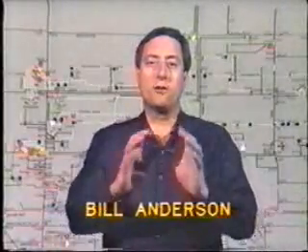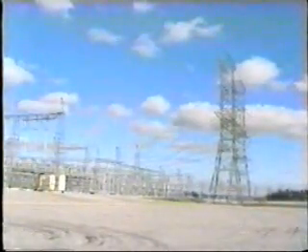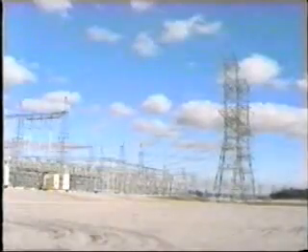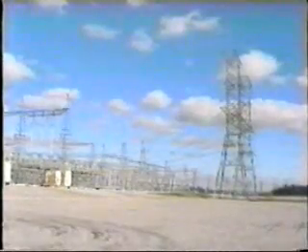As we have learned throughout this program, we are continuously seeking to trip faulty segments of the system as rapidly as possible. We also want to protect 100% of the line by high-speed tripping instead of just 70 or 80%. This is particularly important for high-voltage transmission lines, where a delayed fault could conceivably cause instability of the system, resulting in tripping and clearance of many other transmission lines and generating stations.